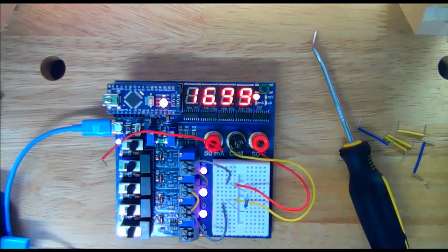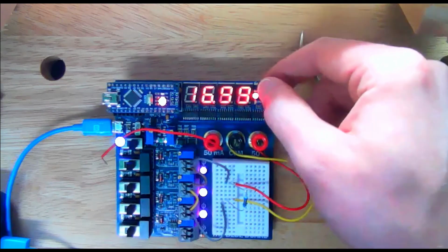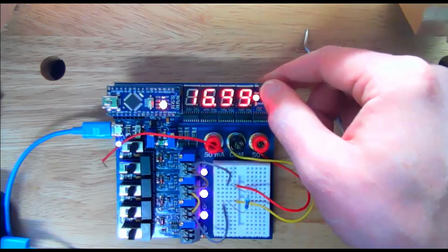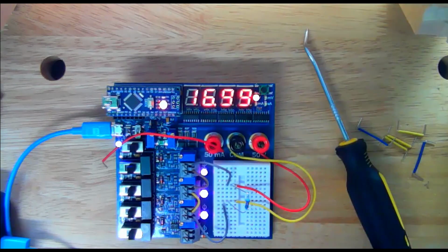High resolution mode basically just averages more data samples. So if you have a noisy measurement, especially if it's a small voltage or a small current, it's going to help you clean that up a little bit. It's going to smooth it out. So if you notice your voltage or current measurements jumping around a lot, you can hit this button until you see the high, and that means you're taking high resolution samples. It's just averaging more samples together.